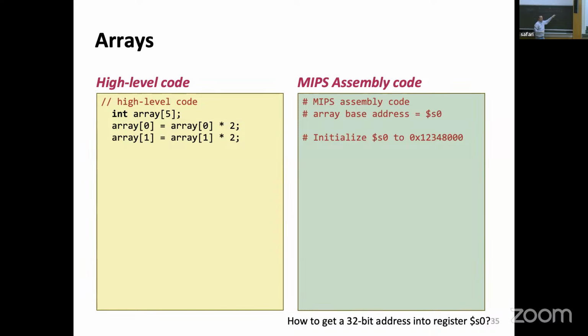Technically, if you think about your combinational logic, if I could OR a value on top of that, I could get it. So there is an instruction called OR immediate, $S0, $S0, and now this is the other number that I want to add. I take this part, which is all zeros, OR it with this, and write it back. And then this would magically turn into 800. So that's 1, 2, 3 steps.